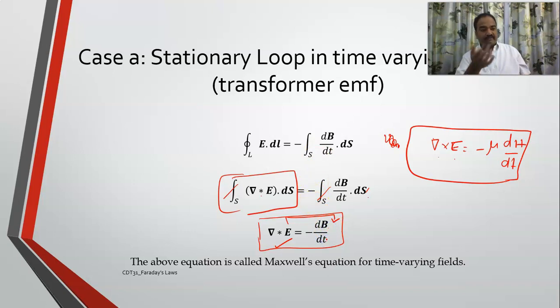Now, let us suppose the magnetic field is constant, because if we have DC currents the magnetic field remains constant. In that case, do we have an EMF generated? No. Normally, when the magnetic field is constant with respect to time and the coil is stationary, we don't get any EMF. Now the second case comes. So once again, repeating for you, there is a conductor placed in a magnetic field. For EMF to be induced, there are three cases. Case 1, conductor is stationary.